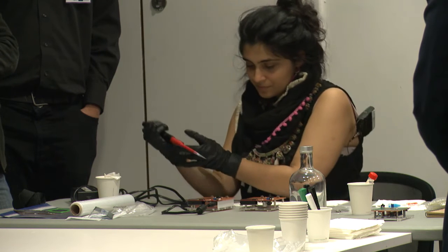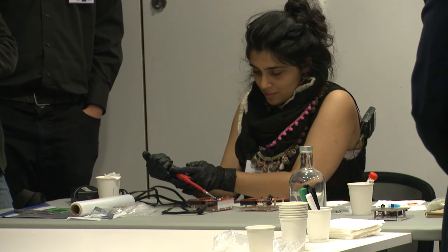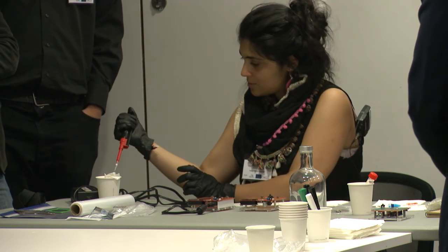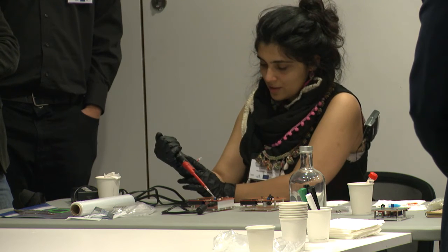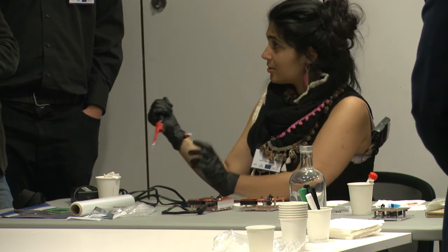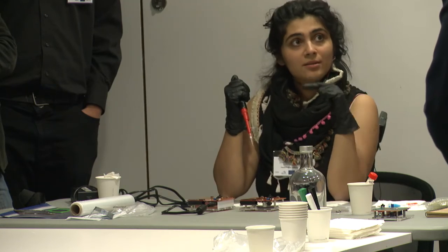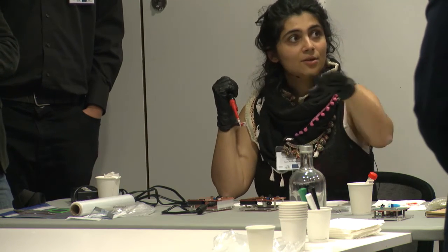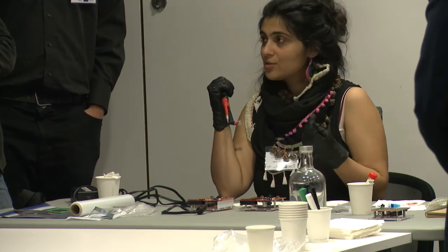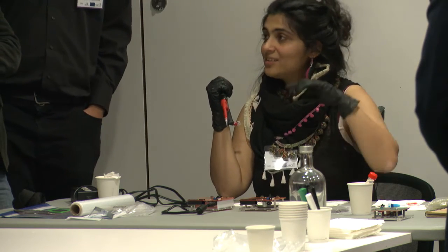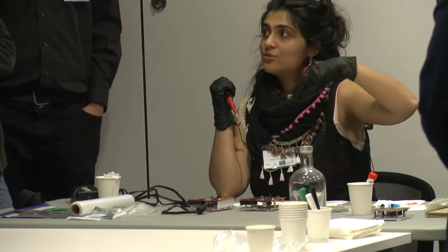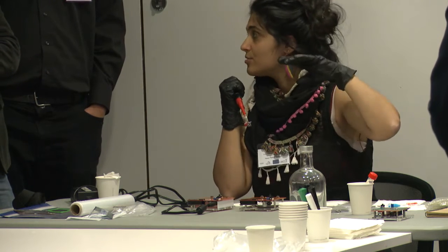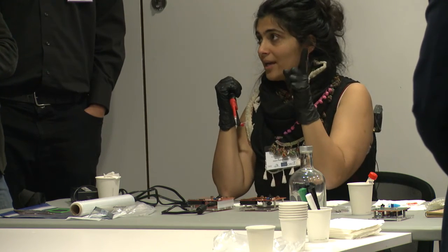Now, somebody asked me in the break, and I think I didn't specify it perfectly, but maybe you can see it here. The droplet has to cover the electrode and the gap between the neighboring electrodes. So it has to be a little bit larger than the electrode at the contact. So the size of the electrode, which depends on the technique we use to make the electrodes, determines the size of the droplet at 1x level.